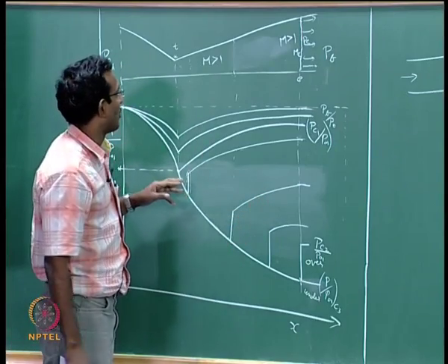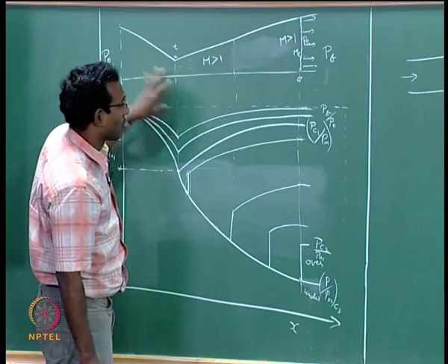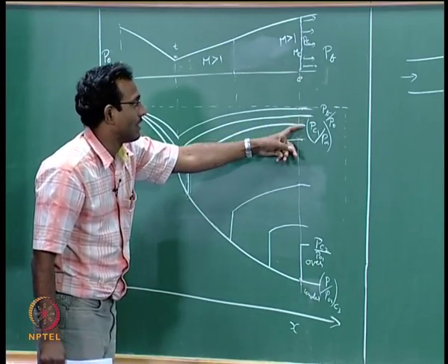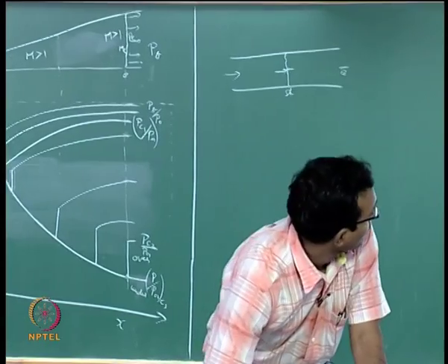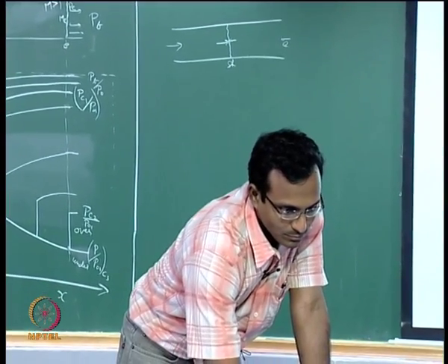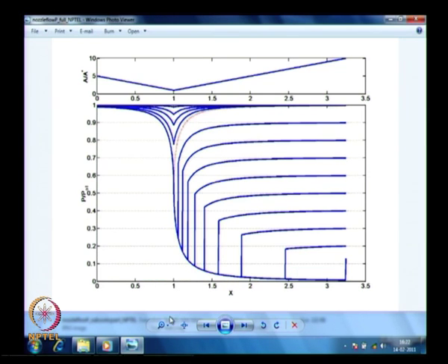Now I go back to our nozzle plots which we had. All this time we plotted only up to above P critical 1 values, what we saw before in the plot. I will go back to the screen. We will look at the remaining plots. We will look at this particular plot where it is again A by A star, the exact same nozzle I am picking, and I have distance here, and P by P naught 1. Now I have to be more specific, P naught 1. All the previous curves I showed are all here, in this region. In fact, I showed you the dotted line also, which corresponds to that 0.9976 number. That is also matching here.